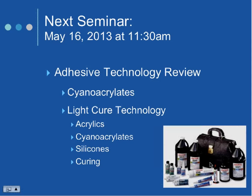So when they cure, you can take a blowtorch to them, and good luck with it. You're just going to char them, but it's really not going to make them go back into a liquid so that you can pull the parts apart. So that's a real challenge with those. With silicones, generally though, the bond strength is fairly weak, so you could actually take a razor blade if you were so inclined and peel that off to a certain extent. The others, epoxies, urethanes, no, probably not.